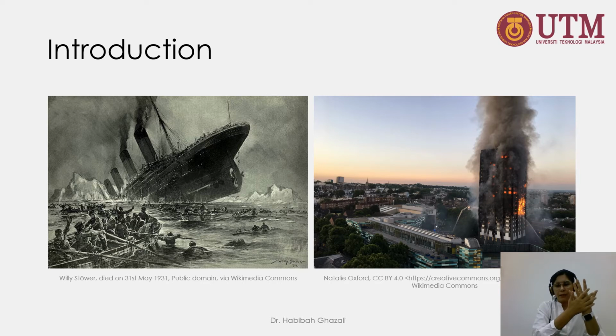So what happened is that a crack that existed in the hull of that ship started to propagate instantaneously, and the ship broke into two, because the steel that they used to build that ship transforms itself from being ductile at higher temperature to being brittle at lower temperature, and it cannot absorb more energy.